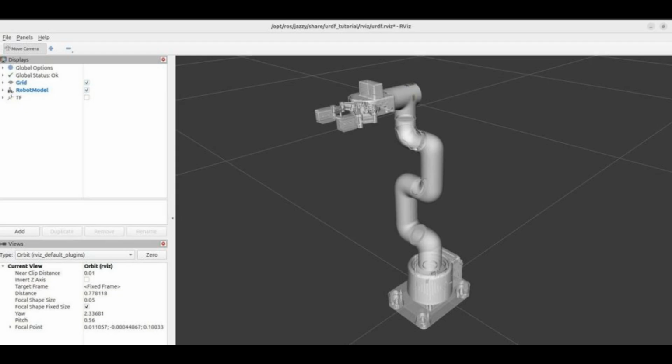Within ROS 2, defining the URDF file of your robotic arm is important because it allows software tools to understand the robot structure, enabling tasks like simulation, motion planning, and sensor data interpretation. It is like giving the robot a digital body that software can interact with. I will walk through all the steps for creating the URDF for the MyCobot 280 robotic arm by Elephant Robotics. Follow along with me, click by click, keystroke by keystroke.